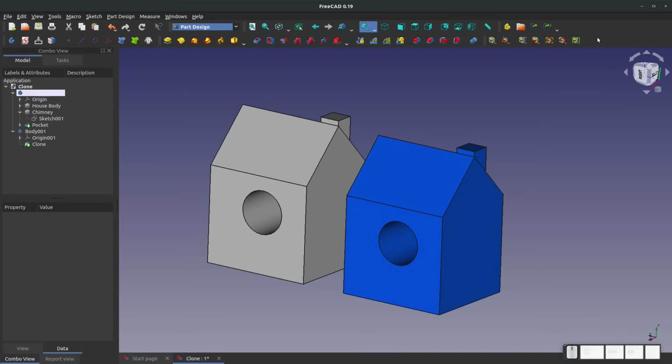So that's how all those measuring tape dimensions work, and we've gone over all of our shape binders, and I think you have an idea of these datums now. We've gone over how to make new parts. We've gone over subtractive and additive primitives. I think we've covered basically every button in the Part Design workbench.